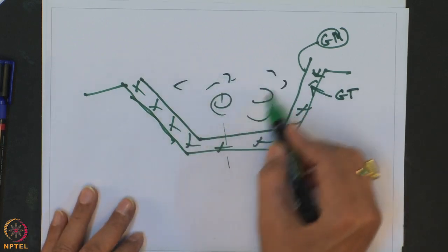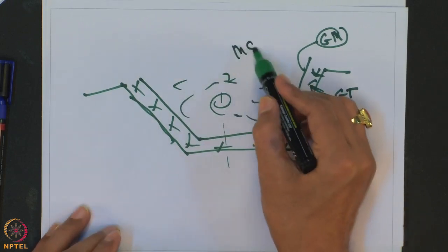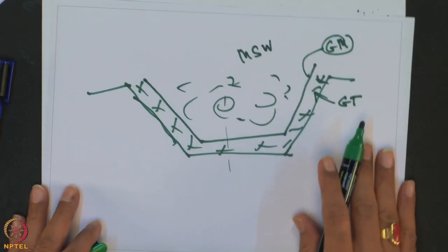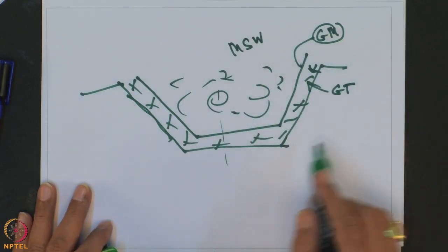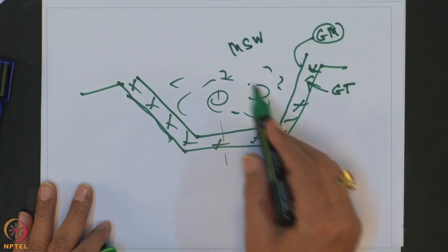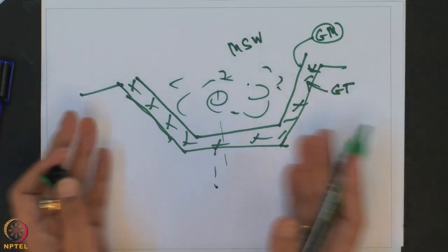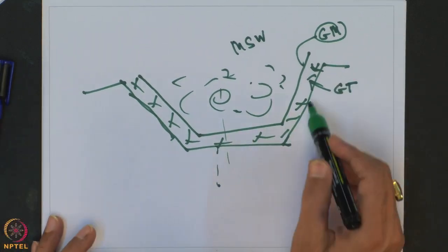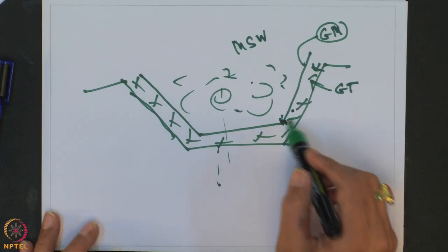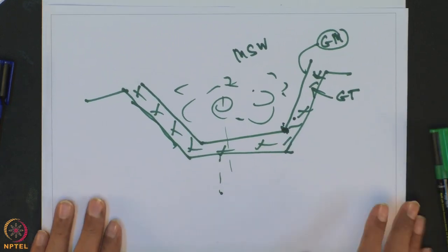So, all kinds of municipal solid waste, industrial waste or low radioactive waste can be contained. There should not be any formation of contamination in the ground, which is the case with the conventional method where we use a compacted clay liner. Here the geomembrane material will act as a barrier. So, you need proper testing, proper thickness of the geomembrane, and proper properties of the geomembrane to select it as a landfill liner. So, here geosynthetic material acts as a barrier.